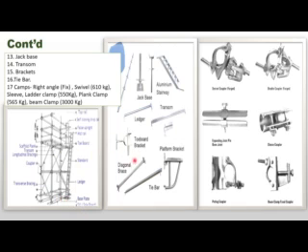Types of couplers. Right angle or swivel couplers, each having 610 kg SWL. Slip and ladder coupler having 550 kg SWL. Plank clamp having 565 kg SWL. Beside this there is beam clamp having 3000 kg SWL, mostly used for hanging scaffold.